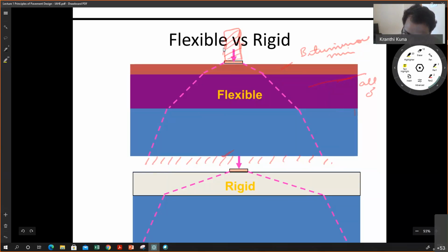For that we put a number of pavement layers. For example, this is the surface, this is the bituminous base, and these are all other layers. As you can see, this one is E1. Assume the elastic modulus of the surface is E1, and the elastic modulus of the third layer is E3. In most cases, particularly in the conventional bituminous pavement, E1 is greater, it is not always true, but in general.